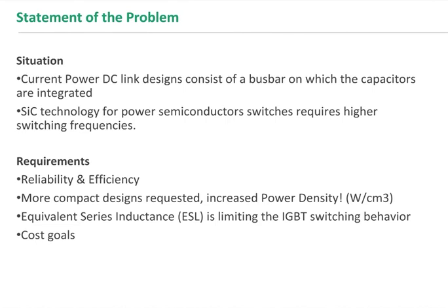That's why we are focusing more on the system, and we look at two components, capacitors and busbars. Capacitors are important during the semiconductor switching, and they are part of a commutation loop, so they have an effect on the behavior of a complete inverter in specific applications. And the overall goal is to reduce this inductance, and that's something you will see on the next slides.